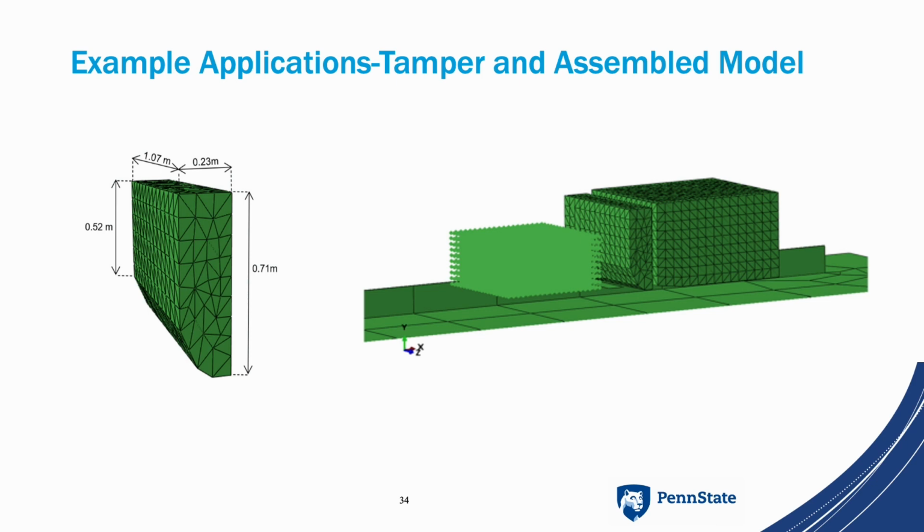As you can see, the paver was placed on the far right side of the base and moved to the left in the forward direction. The tamper and the particle generator were placed in the middle of the specified route. The distance between the lowest part of the tamper and screed and the base was set at 0.4 meter, which was the thickness of the asphalt mixture initially required to be paved. In front of the paver, the particle generator served as both an unloading truck and the paver blades. The particle generator has almost the same width as the paver body, ensuring that the particles are equally distributed over the road to be paved.